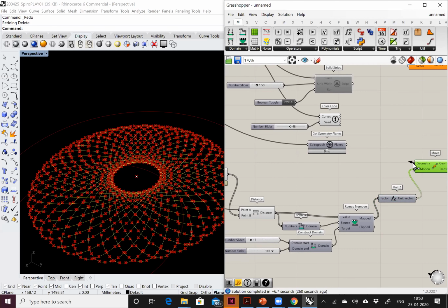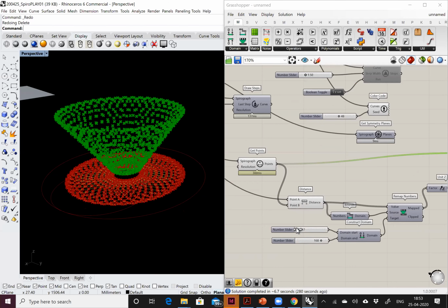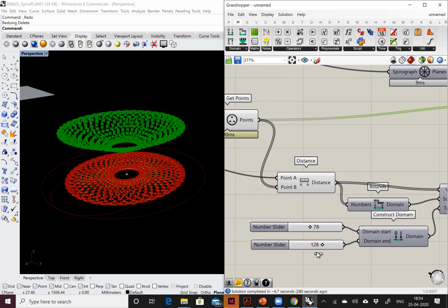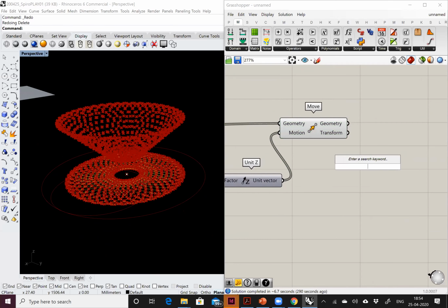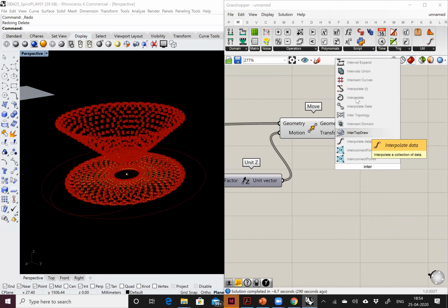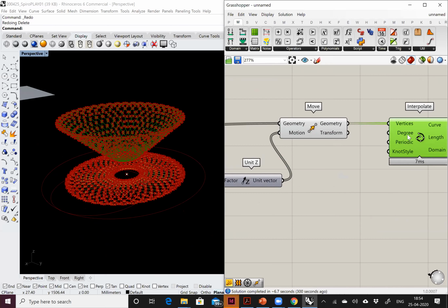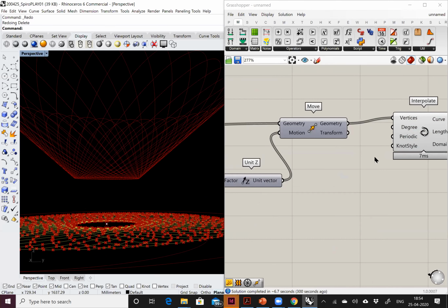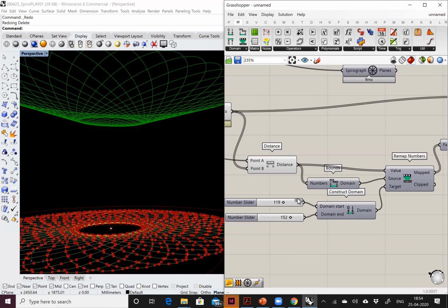And I can use that in the z-axis, these being my points. So essentially, I'm able to move my points based on the center point, and I'm able to make this symmetrical kind of three-dimensional pattern. If I now use an interpolate curve and draw this into a periodic curve, here you can see this is my spirograph, which is three-dimensional right now, and I'm able to control it.